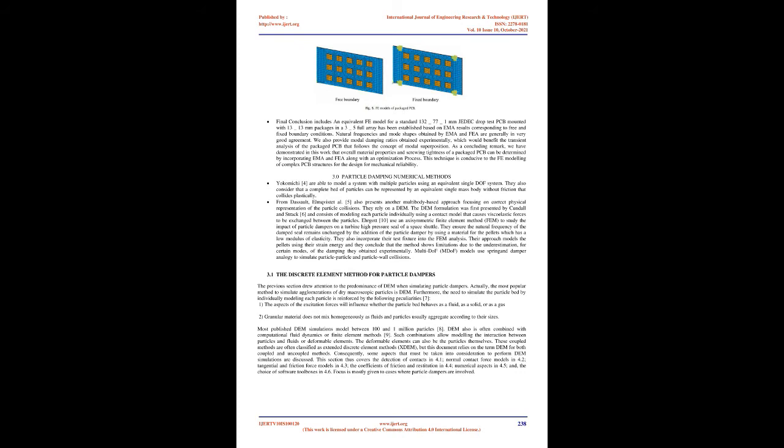boundary condition. The final conclusion includes an equivalent FEM model for a standard 132×77×1 mm JEDEC drop test PCB mounted with 13×13 mm packages in a 3×5 full array, which has been established based on EMA results corresponding to free and fixed boundary conditions. Natural frequencies and mode shapes obtained by EMA and FIA are generally in very good agreement. We also provide modal damping ratios obtained experimentally, which would benefit the transient analysis of the packaged PCB that follows the concept of modal superposition.